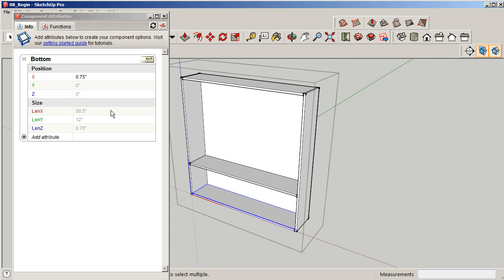What we want is this to be our cabinet width, which is 5 feet, minus 2 times the material thickness. Why that? Because 0.75 here, material thickness, 0.75 material thickness here. That's 2 of them. So we want this entire width minus 2 of those, which will always give us this length, because this needs to fit in between those two pieces.